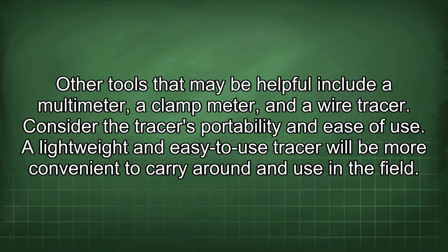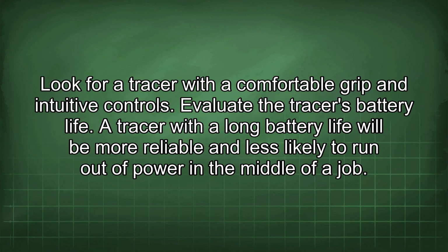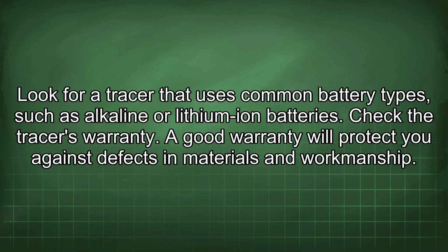Consider the tracer's portability and ease of use. A lightweight and easy-to-use tracer will be more convenient to carry around and use in the field. Look for a tracer with a comfortable grip and intuitive controls. Evaluate the tracer's battery life. A tracer with a long battery life will be more reliable and less likely to run out of power in the middle of a job. Look for a tracer that uses common battery types, such as alkaline or lithium-ion batteries.